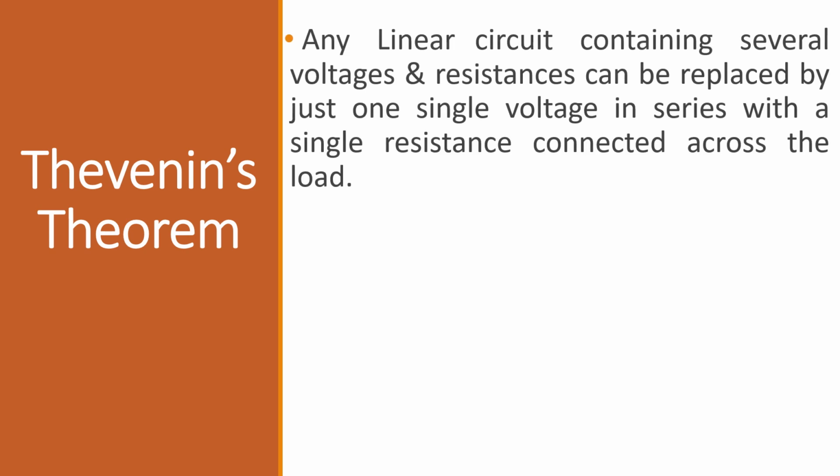Now we will look at Thevenin's theorem. It is an analytical method to change a complex circuit into a simple equivalent circuit. It states that any linear circuit containing several voltages and resistances can be replaced by just one single voltage in series with a single resistance connected across the load.